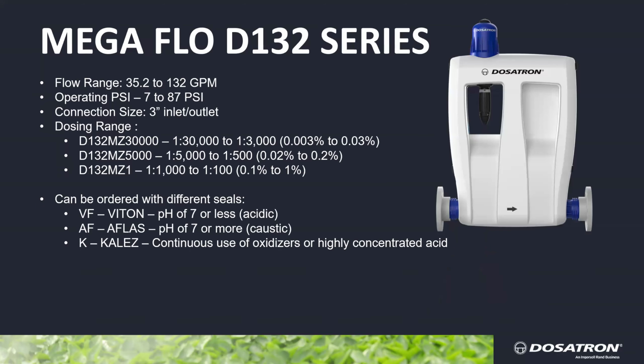If we need to go higher than 100 gallons a minute, our next one in the MegaFlow series is our D132. Our D132 operates in a flow range of 35.2 to 132 gallons per minute. And our PSI is 7 to 87 PSI. Connection size is 3-inch inlet outlet.